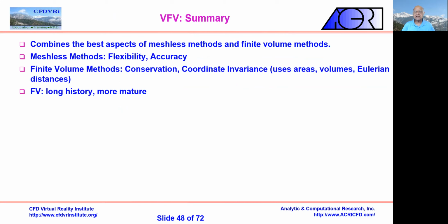So what virtual finite volume does is that it starts like the typical point distributed meshless method. We distribute a number of arbitrary points, right? SPH would deal differently with it, and least squares would deal differently with it, but they form a collection of points at which gradients are computed to satisfy the equation. What we are saying is we already know that finite volumes work very well, preserve local conservation, and they have some other advantages. So why not, behind the scenes, without the user knowing, construct a grid which is finite volume, but the user only sees a point. User doesn't care that I have to build a grid. User doesn't build the grid. The grid is built by the system from those points. And many other meshless methods actually are building a grid behind, just like we are doing here with virtual finite volume. So this technique is used by others too. Just their functionals are different and their way of dealing with it.